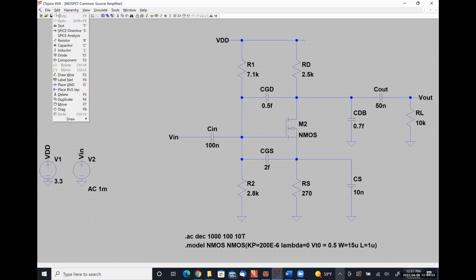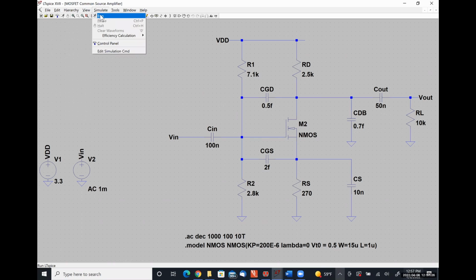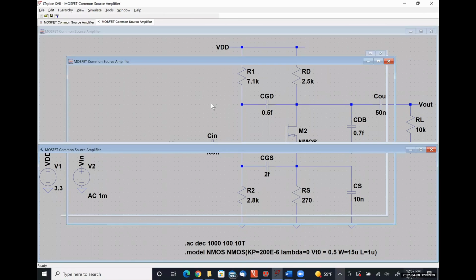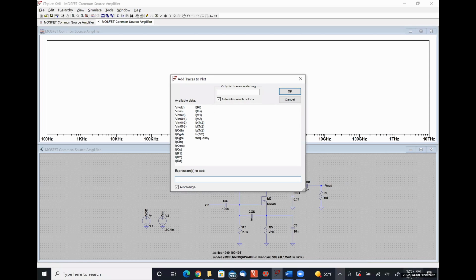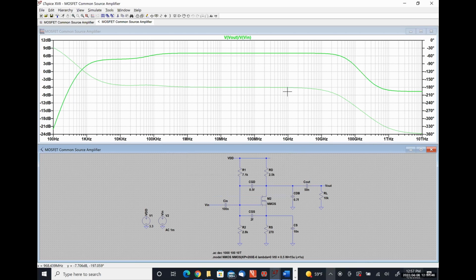And if I simulate this, that is not a division sign. That would have probably done something wackadoo. The left, and I've expanded out the frequency, right? So instead of starting at 1 kilohertz and ending at 1 gigahertz, I had to go all the way out into the terahertz range for us to see the actual high frequency roll off here with just those capacitors.